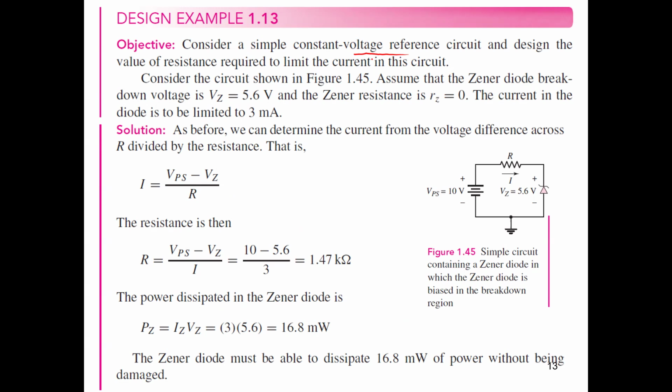If the volt is higher than the reference, I should make a certain action. If the volt is lower than the reference, I should do the opposite action. But where is the reference? Where can I get the reference? The reference can be obtained from a Zener diode. So this is the benefit of having a constant voltage reference in our life.